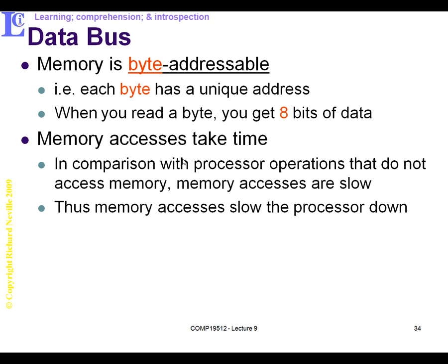When you move outside the processor via the address bus and connect to the memories, these are running at a slower rate, which we've already implicitly seen, because when we've been undertaking memory reads and writes, they've been taking 3 processor clock cycles. So the memory in a system is slower than the processor.